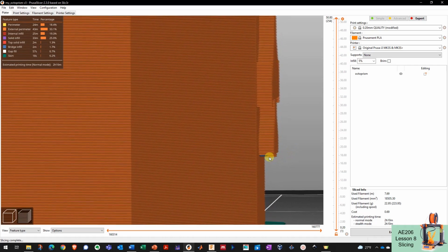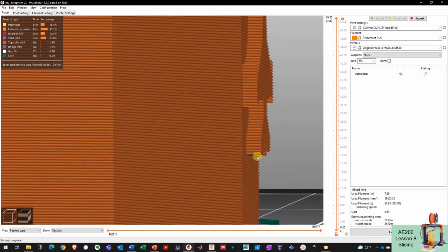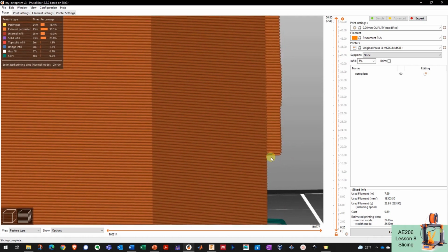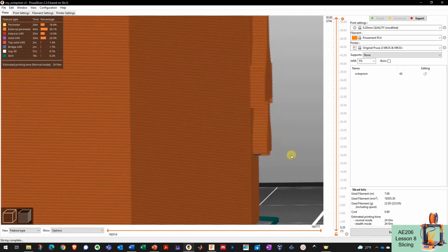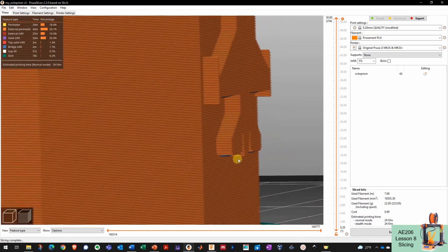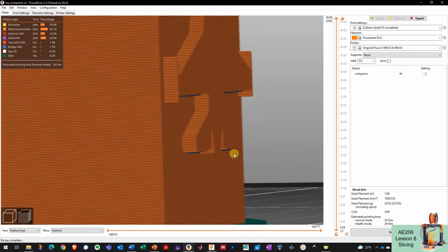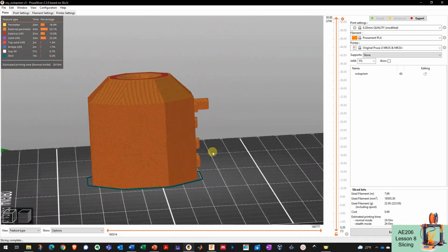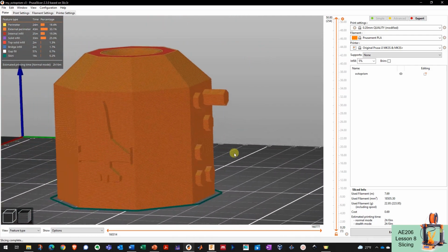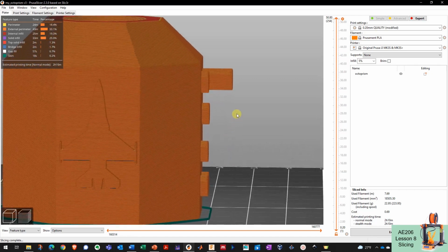This small of an overhang, the printer will extrude some plastic there, but it won't start drooping down very much because it's such a small overhang, and then the next layer will come out fine. So at the most, there might be one layer here that looks a little bit strange, but you're not even going to be able to notice it unless you're looking for it. And of course, now that I've said it, you will look for it, but it's otherwise fine.